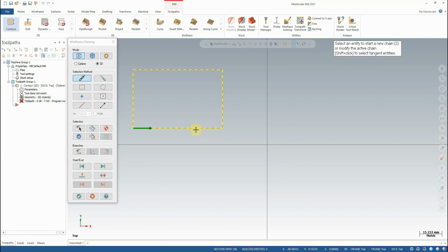This is important because when we are milling an external feature, it's usually best to chain in a clockwise direction. And when we're chaining an internal feature, we generally want to chain in a counterclockwise direction. The reason for this is that on standard machines, we would be cutting with right-hand tooling, rotating the tool clockwise, like this. As the tool comes along beside a part, if it's traveling in this direction, it's going to be doing what would be considered conventional milling.